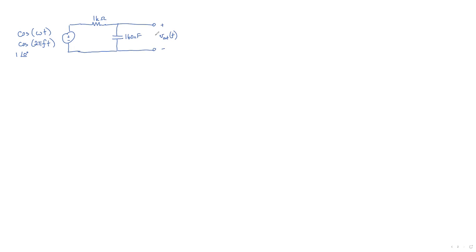So first, realize that up here we're in the time domain. We're talking about the capacitor being a 160 nanofarad capacitor, not a generalized frequency-dependent impedance. And we're using lowercase outputs as a function of time, and voltage sources that are a function of time, for the input. Now, what we want to do is see how this output changes versus frequency. So we'd like to plot that peak voltage, which is a number, even though this waveform, of course, looks like this coming out of it. We're interested in plotting what that peak voltage is, Vp, versus not time now, but versus frequency. So as we increase frequency, how does that change?